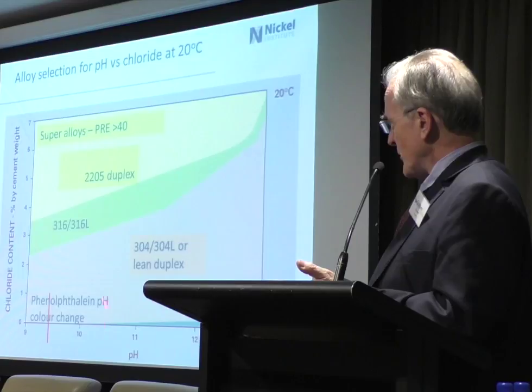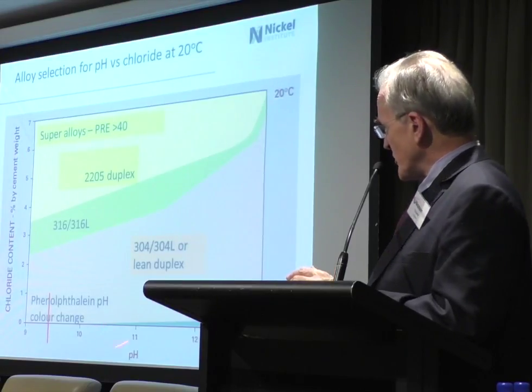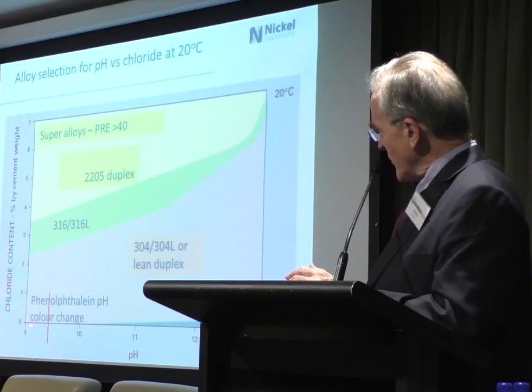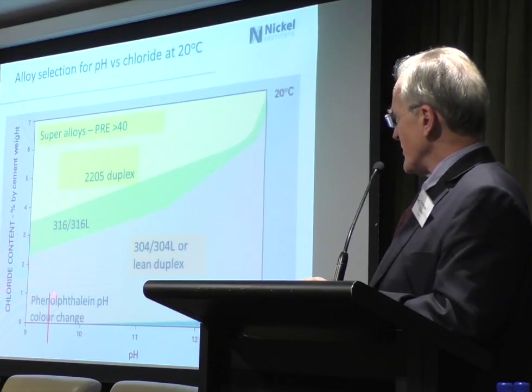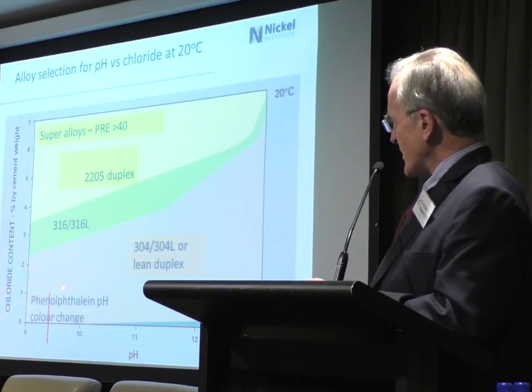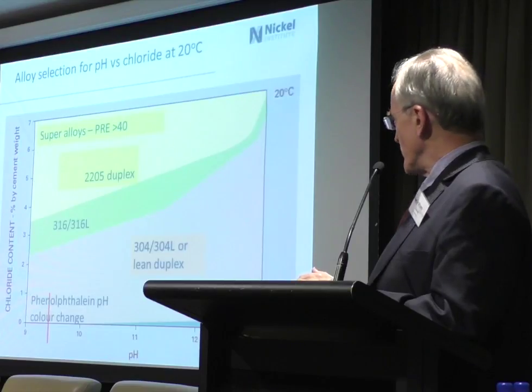And that's where our carbonation change comes. And as you can see, it's right past the end of where the carbon steel is corroding furiously. So just because it has only just changed doesn't mean that the carbon steel is not in deep, deep doo-doo.